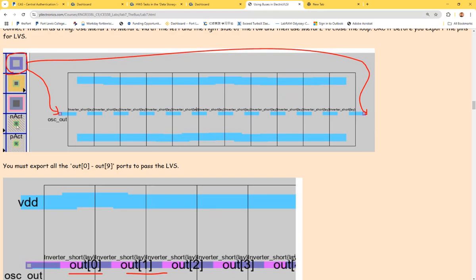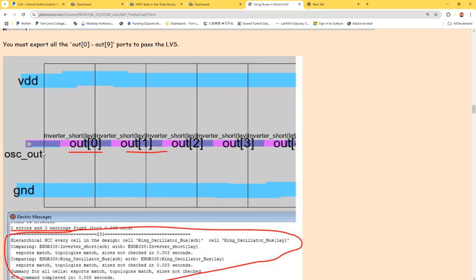So this is the technique to introduce metal 2 into a circuit. These are vias, right? These are metal 1 to metal 2 vias. You drag a via and place it here, because this is the metal 1 to metal 2 via, so it's able to connect metal 1 and metal 2. You drag a little via here, and you left click and right click to make a connection to the metal 1 wire for the input of the first one, and you do the same thing for the output of the last one. Eventually you introduce the metal 2 in the middle, which is not going to affect anything because it's on top. So that's how I did it.